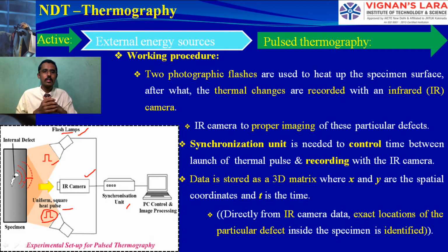We are not scanning. It's not X-ray. We are not using a magnetic field. We are not using any liquid penetrant inspection. It is such a type of wave understanding. So we are sending heat from the flash lamps, it goes in and comes back. We observe that with the infrared cameras, and the data is plotted in 3D format and analyzed on the computer. See there, it is synchronizing data, and it is PC controlled image processing in 3D formats. That's what is also written here.